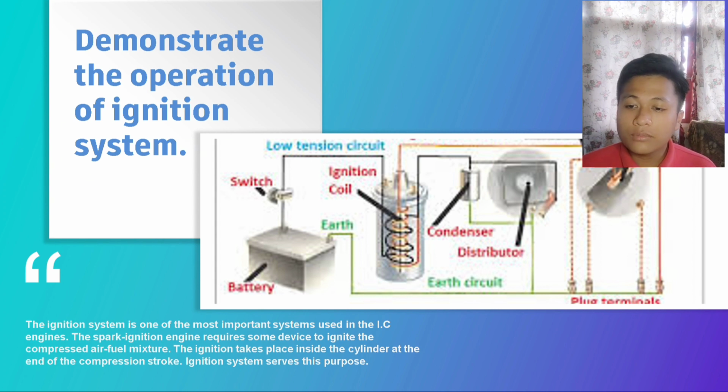The battery ignition system is mostly used in passenger cars and light trucks. In the battery ignition system, the current in the primary winding is supplied by the battery, while in the magneto ignition system, the magneto produces and supplies the current in the primary winding. The parts of an ignition system are: battery, switch, ignition distributor, ignition coil, spark plugs, and necessary wiring. Some systems use a transistor to reduce the load on the distributor contact points. Other systems use a combination of transistor and a magnetic pickup distributor.